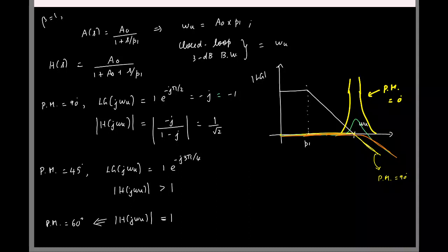Okay, so there's one other criteria for choosing phase margin. So now we know that for the closed loop system, we want the poles to be lying on, where do you want the poles to be lying on? LHP, yeah. You try to keep it on the real axis, right? Yeah, negative real axis. And from the root locus plot, you remember that the open loop poles were somewhere here, far apart. They did this and branched out like this, right?